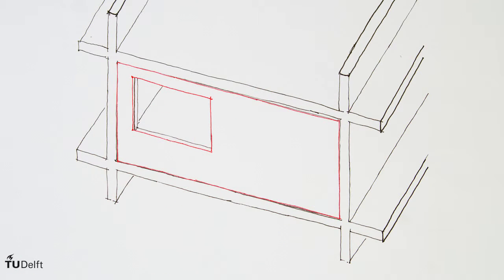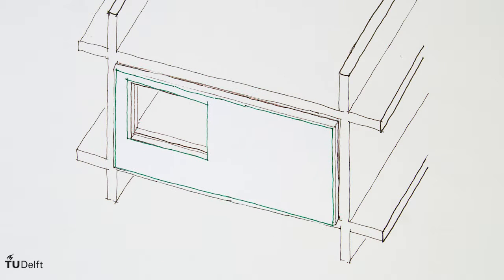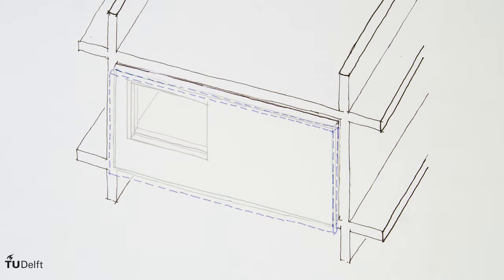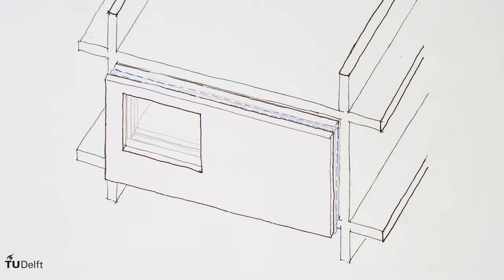The second group has a thermal insulating function and regulates moisture transport within the construction. In many cases there is a gap between the thermal insulating layer and the outer layer, a cavity which has a function in the regulation of moisture. The outer layer group has the function of rain screen, a static layer, UV protection and impact protection.